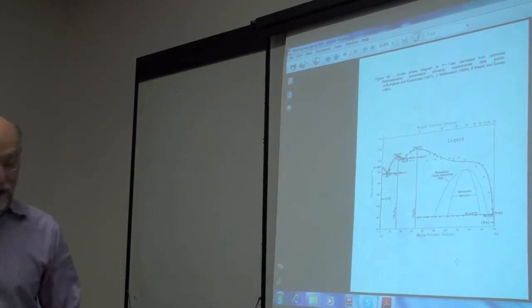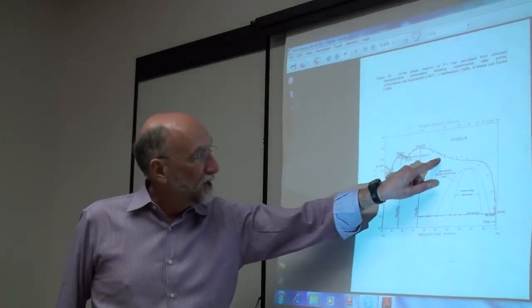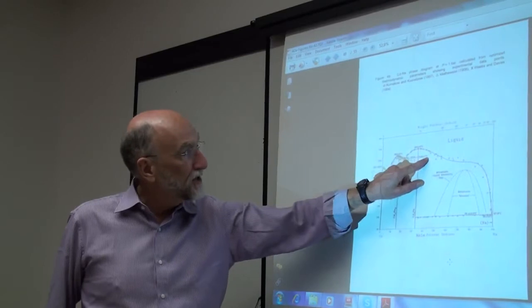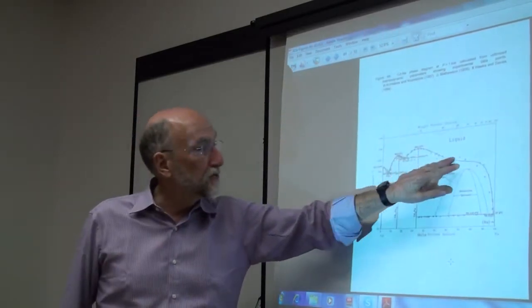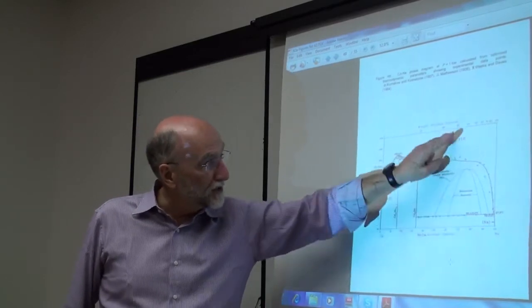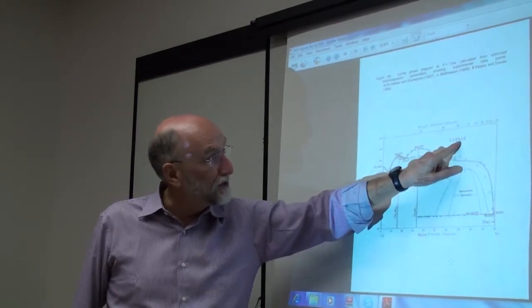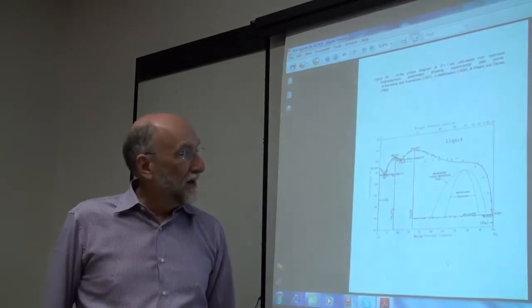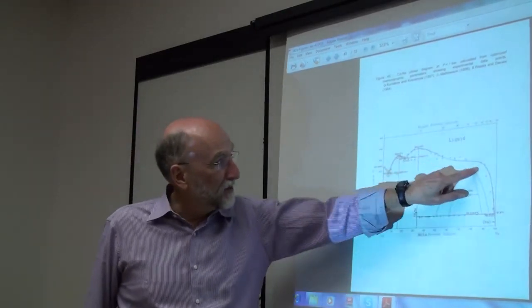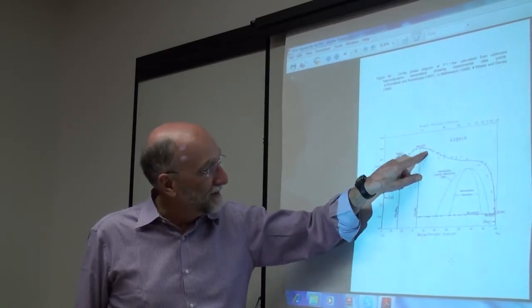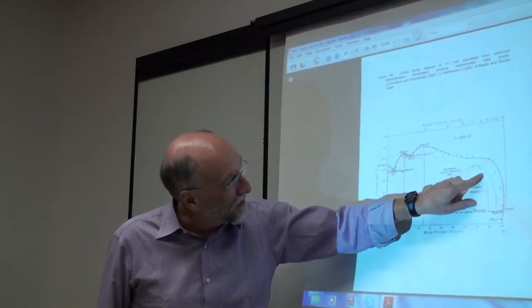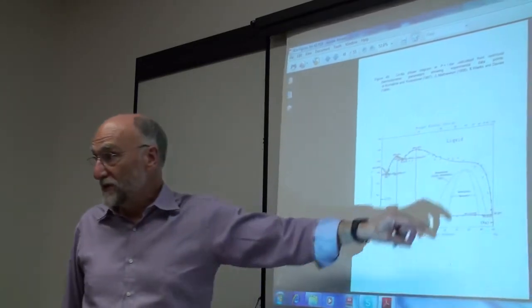Okay, anyway, that's not the optimization. What else? So you have these experimental data points. Actually, you see that one experimenter here, the triangles, made a flat here. In other words, he thought there really was a miscibility gap extending above the liquidus. He thought that the critical point here was above the liquidus temperature. And really, given all of these points and the scatter of the points, that is possible. It is possible to interpret this as coming up above the liquidus temperature.